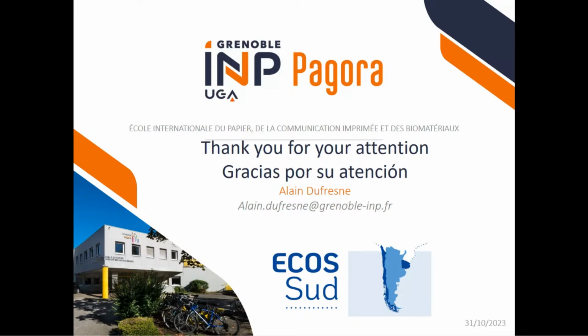For this aspect ratio, we have what is called a percolation effect, or interaction between the nanoparticles, from 1% by volume. Of course, if the aspect ratio is lower, for example in the case of cotton, the percolation threshold, or the content of nanocrystals necessary to form this network, is higher. I don't remember, it's maybe 7% or something like that. Yeah, I understand. And that leads me to another question. Does that mean that they have to interact somehow, like through hydrogen bonding?